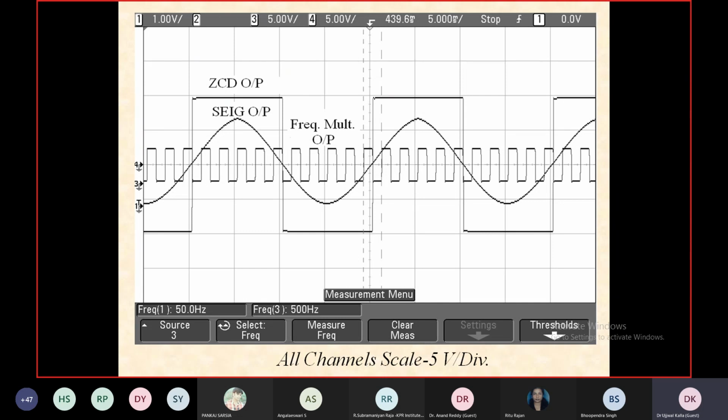That is also very important practically. If you are multiplying a signal with a scaling factor of 5 or 10, meaning 5 times or 10 times, both the waveforms should be locked, input and output waveform in phase. If they are not phase locked, the multiplication will sometimes be 10.1 times, 10.2 times, maybe 9.9 times, maybe 9.8 times, but it will not be exactly 10 times.